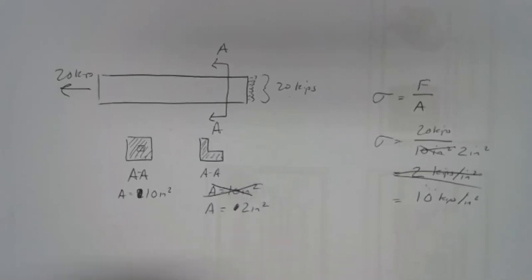You can think of it kind of along the lines of what you did figuring out wires and what gauge wire to use. Sure, we could run 4/0 to everything, have quarter size welding cables running to everything, and it would work, but it would involve a lot of copper and cost a lot of money when all we need is an 18 gauge wire to do the job or a 12 gauge wire to do the job. So we have to balance the objectives of safety and of waste and cost.